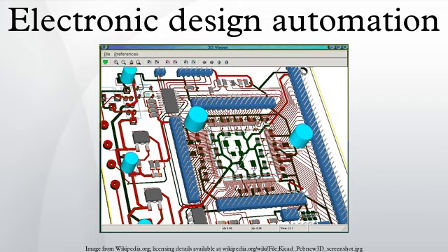Equivalence checking, algorithmic comparison between a chip's RTL description and synthesized gate netlist, to ensure functional equivalence at the logical level. Static timing analysis, analysis of the timing of a circuit in an input-independent manner, hence finding a worst case over all possible inputs. Physical verification, PV, checking if a design is physically manufacturable, and that the resulting chips will not have any function-preventing physical defects, and will meet original specifications.